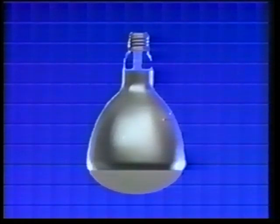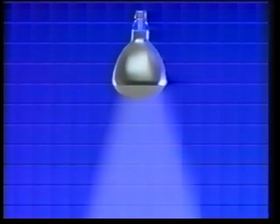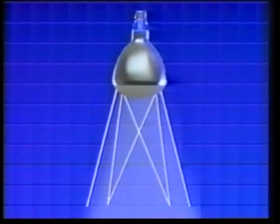The ER lamp, or ellipsoidal reflector, was developed for very special applications. The special optics of the ER lamp create a crossover of light just in front of the lamp. This allows a designer to create a fixture with an opening smaller than the diameter of the lamp. The lamp can then provide full output while the fixture shields it and prevents glaring.